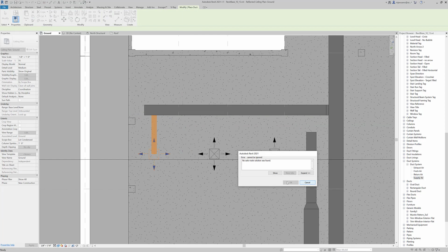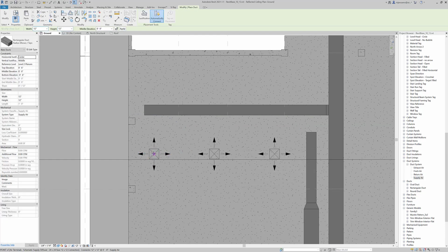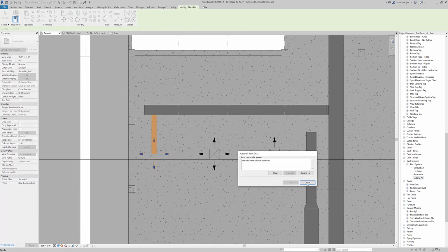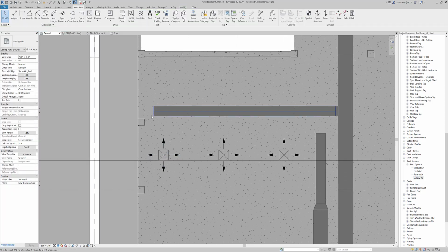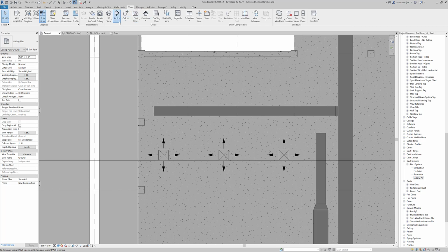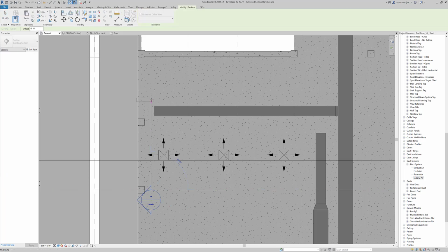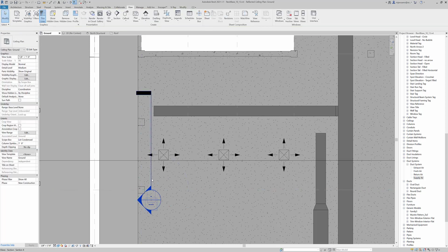Now it's probably not going to find a correct auto route solution. It's not 100% impossible that it finds one, but let's look into some of the difficulties of routing the air terminal into one of the ducts. I'm going to go into view and make a section view that looks directly at this connection.